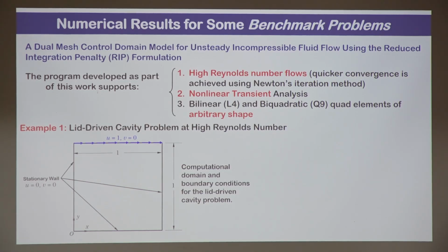What exactly is happening? Think of a belt going over this cavity. You're running a motor and the belt is moving. So the viscous particle is stuck to the belt just from 0 plus. If this coordinate here is 0, 0 plus is where it is on the belt. But here it is not, right? So a tan hyperbolic function can describe the boundary conditions very nicely, going to 0 right at these points. But anyway, we did study with U equal to 1 here, and U equal to 0 also, at the end points.